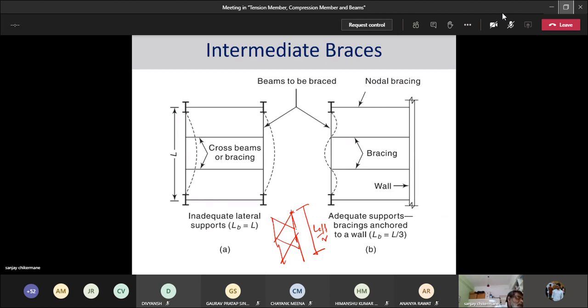And at a local level, you ended up getting a much smaller L, which needed to be addressed. Similarly, when you're doing bracing on a beam, you have got a compression flange, and then you want to apply braces so that the effective length of the compression span becomes less than the actual L of the beam.